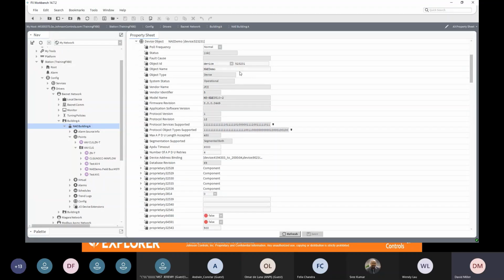If it's an MSTP device, it'll have a dip switch set to something in the range 4 through 127. That's its MAC address. So typically for a device ID number, if its MAC address was 25, you might make it 1025 for trunk number 1.